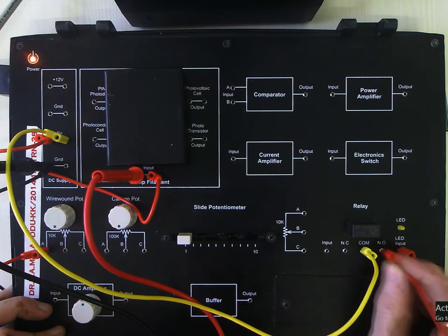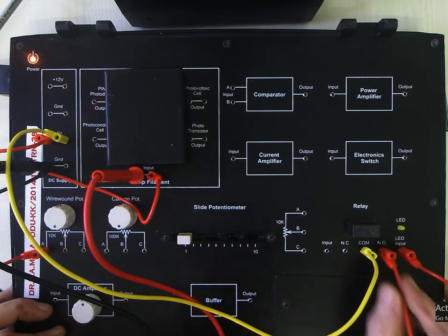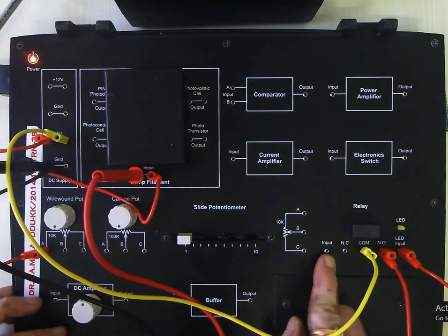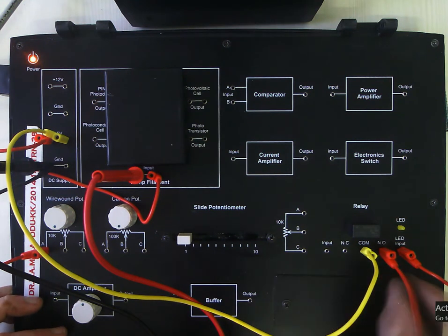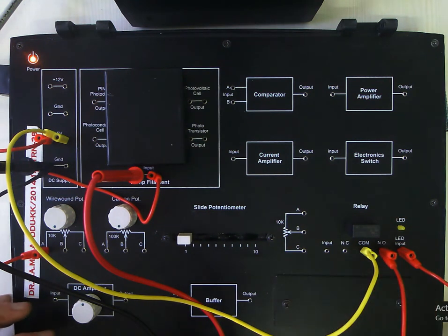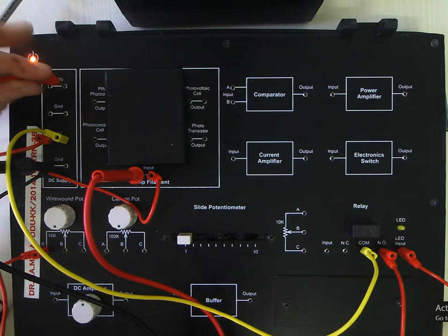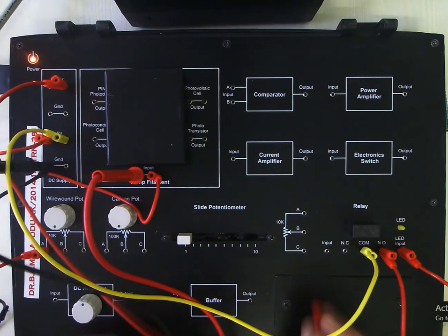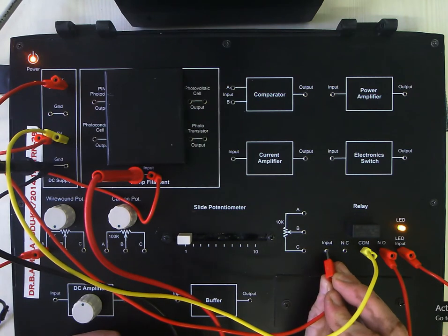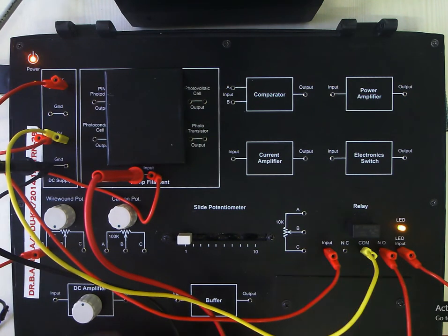So what we will do? We will now connect the LED to the NO, and now we will try to energize the relay or the coil. For that I will be using this 12 volt, which is an onboard facility. I will give it to the input. Now you can find,